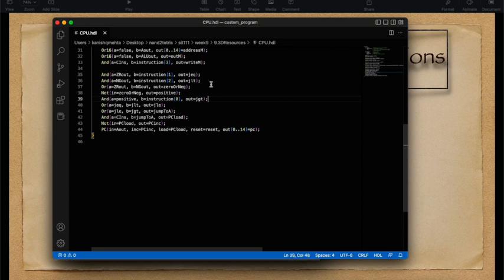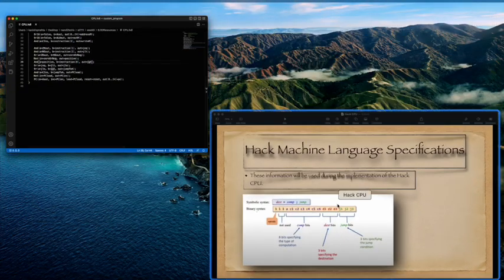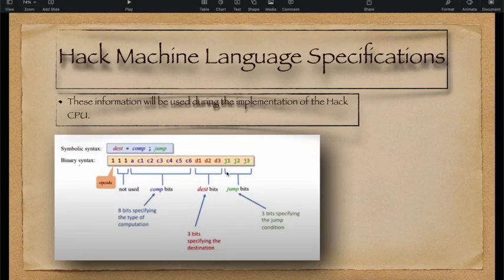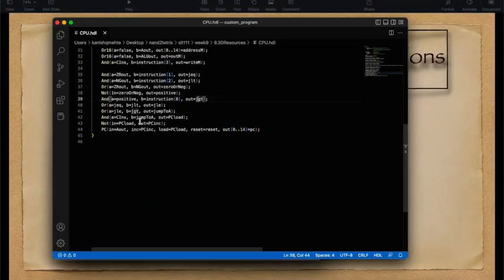So we have a total of 8 jump instructions, and the last three jump bits control all these jump instructions. Next is our OR gate, which will load the jump equal and less than and help in execution of the jump less than or equal to instruction. Next is our OR gate, which will load jump less than or equal to and greater than, and helps in controlling the jump to A, that is, whether it needs to jump to A or not.